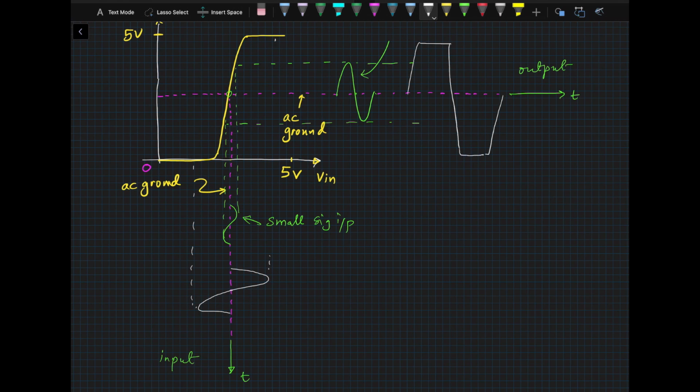Okay, purely by tracing the waveform, you can see that this is where the output is at VDD or ground. So this is highly undesirable because this is called clipping, and this clipping creates distortion. One good example would be, let's say you take an amplifier or a mic, and then you scream into the microphone.